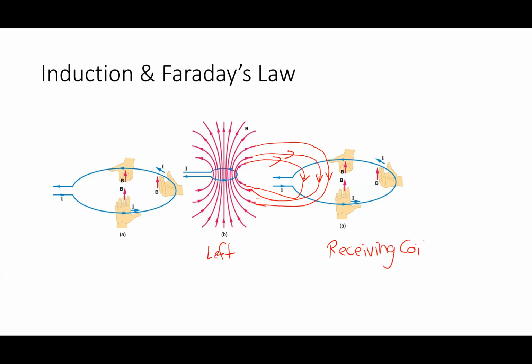How well am I doing at directing the magnetic field into that coil? Not very well at all, right? If my job is to basically direct the magnetic field into the coil over there, I haven't done a very good job. What I probably want to do is direct that field to go from the coil where I'm putting it in to the coil where it's coming out, right? So what would be a good way to do that? Even if I put the two coils on top of each other, which you could do, it still would have a fair amount of what I call leakage, where some of the field wouldn't couple into the other one.